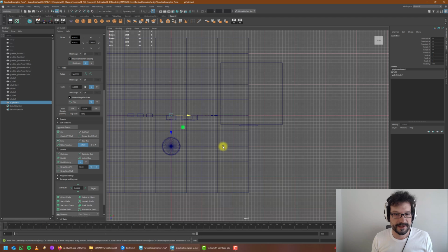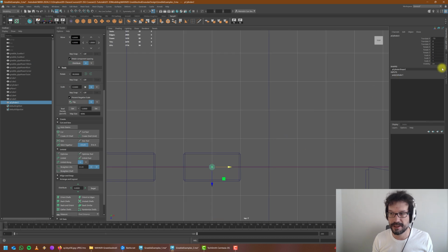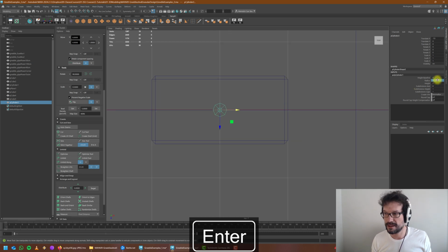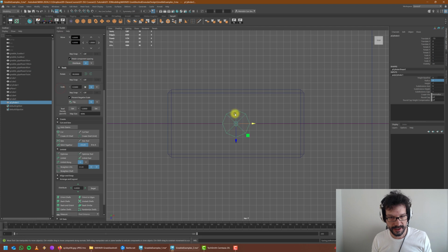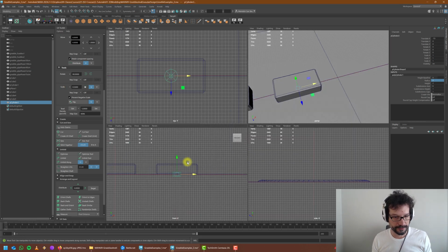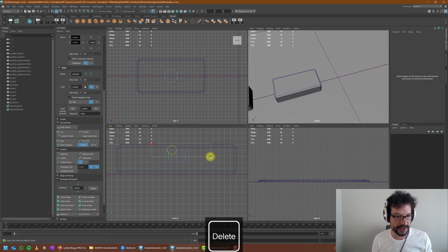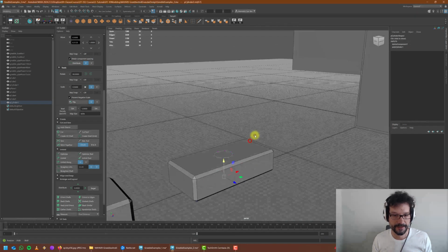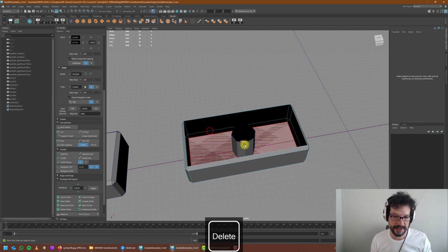So let's create a cylinder. I'm going to make the cylinder even less detailed than the other ones, like 8 faces. Let's give it a slightly bigger radius, maybe even 2. Why not? So let's do this. Okay, and let's grab these faces, delete them because we're not going to use them. I mean, the face underneath, we're not going to bother with it. And the face, let me delete this.